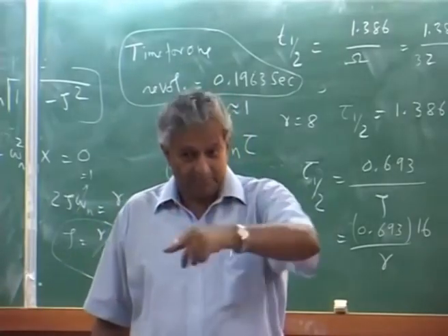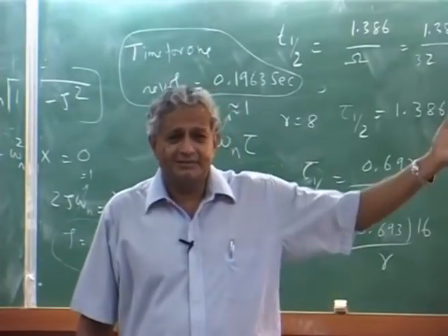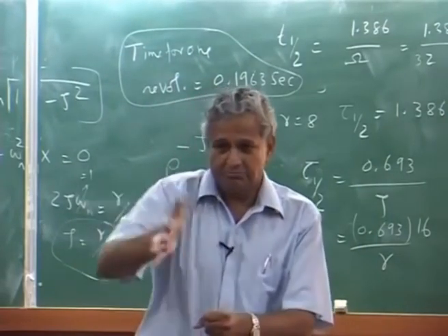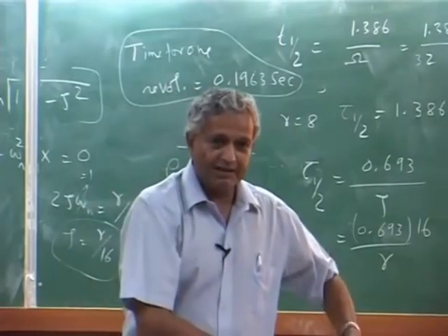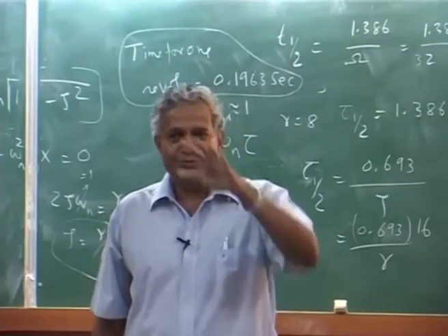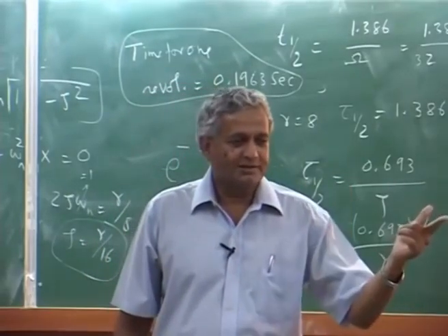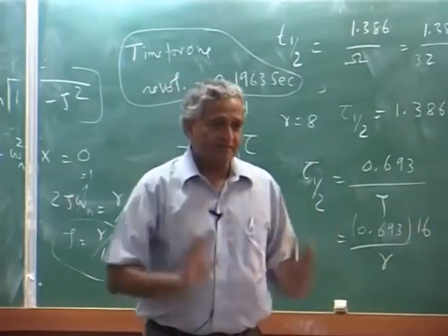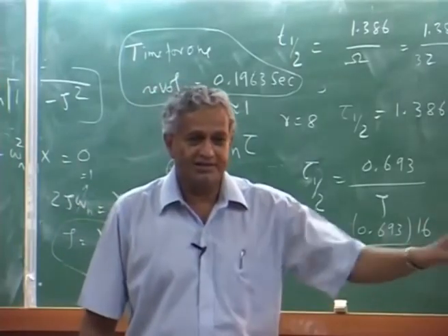Now I am coming to flight dynamics. The pilot gives an input to the rotor blade, the blade immediately flaps, then it gives the hub moments and the helicopter responds. The delay between pilot input and the response of the blade, I am neglecting. I say that it responds instantaneously. That means I neglect the flap dynamics and look at the steady state value.